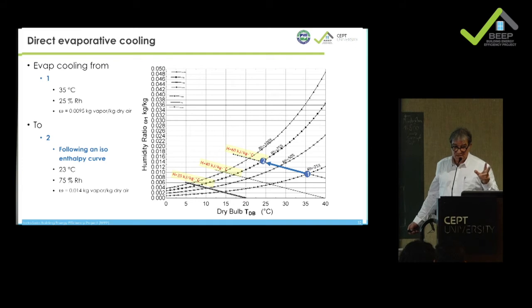You follow this, so it is. Remember there are these horizontal lines for sensible heating and cooling. So just to show you again, sensible cooling is if you have a kind of cooling coil, but with water maybe at 16 degrees, not at 6 degrees, then you would cool without condensing the water.